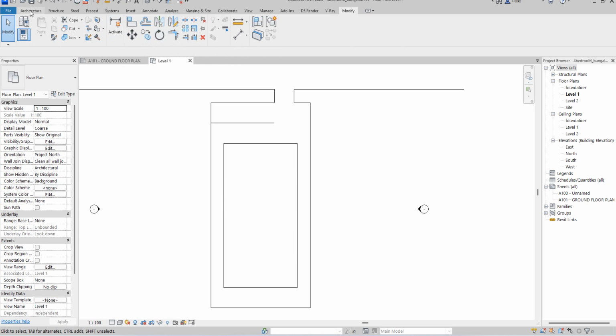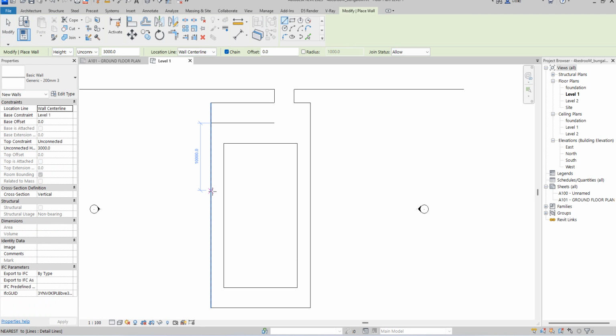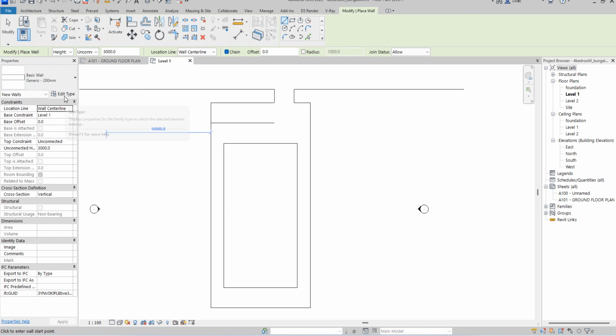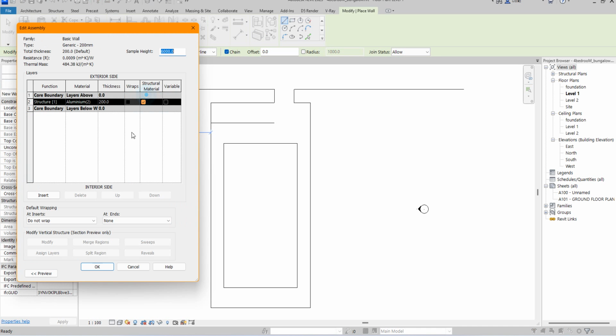So I'm going to start my work by saying components. I will change it specifically here. Then I will go, if I have what it takes. So this is particularly the width of 200. I want to change it to the normal standard of what? Of 9 inches, which is what? 225. So we commonly use that one in Nigeria because that's the normal size of block, and we have to